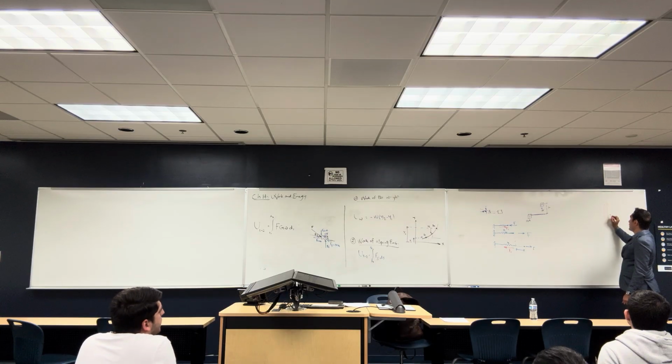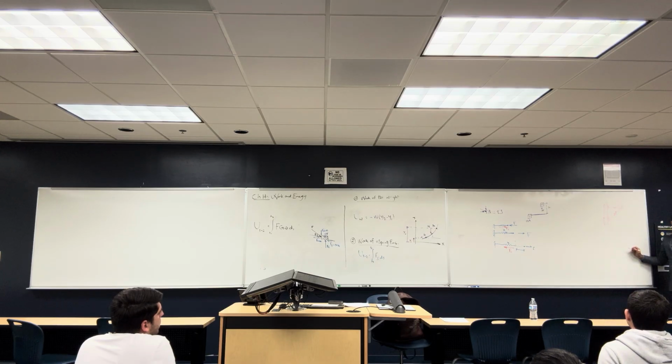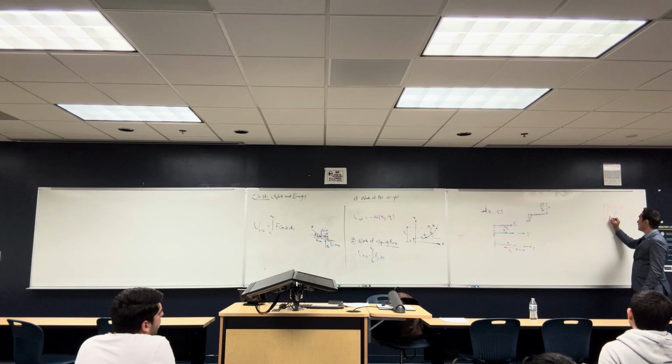I was thinking about it, like you have a collar here and you have a spring here, and somehow your body is moving down and the spring is something like this. The thing is, only one component of this spring is contributing to the work on this body to move up and down. If you get the two components, let's say this is theta, so F spring has this one as F cosine theta, and this as F sine theta.